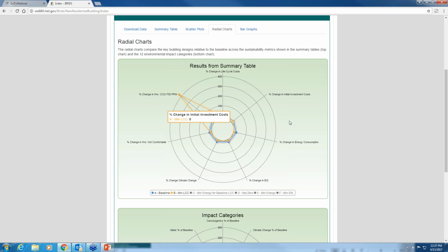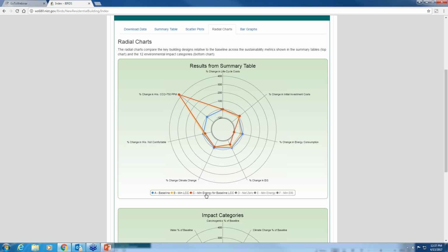So by improving energy efficiency, making the building tighter so you have less infiltration leads to a concern for pollutants in the air inside the house. And so that's something you have to think about when it comes to designing these low energy homes. And then, so moving on to the next point.